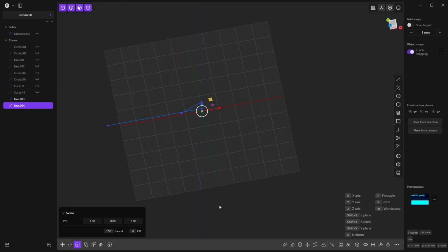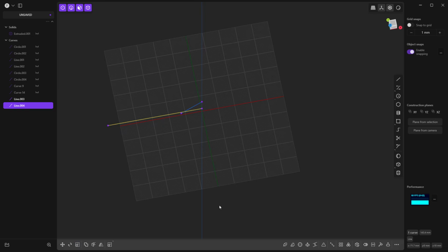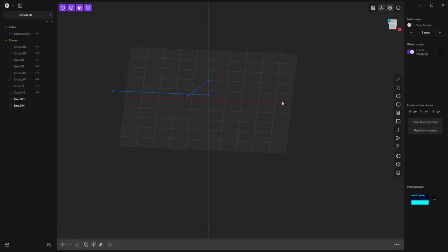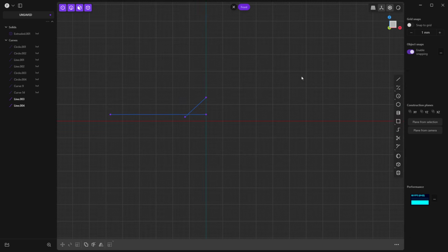We're going to leave the scale in X and Z the same. What this actually does is it scales it all the way down to where our cursor was so that Y equals 0. Because the geometry isn't actually going to change in that orientation, all it's doing is pushing it down to 0 without needing a snap location for where those points are.